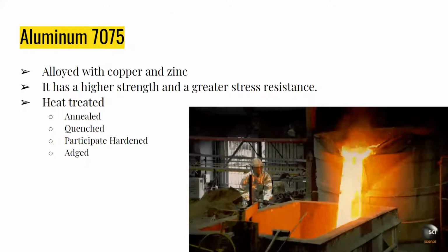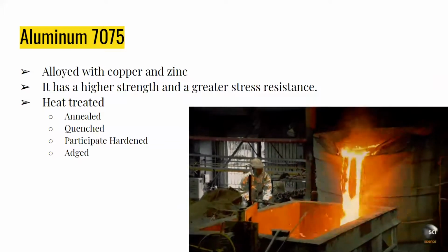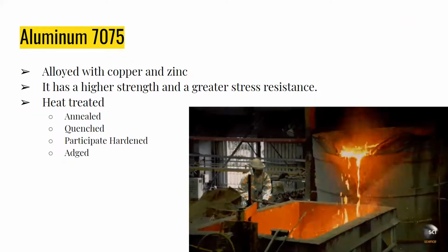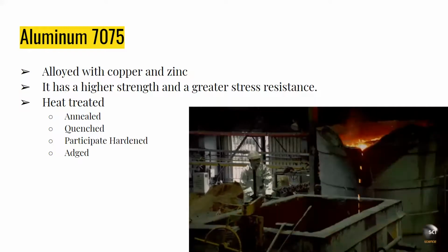Another widely used material is 7075 aluminum. This material is alloyed with copper and zinc for maximum tensile strength after heat treating. It is used for areas that experience a lot of stress because it is one of the strongest alloys available. The alloy has a great strength-to-weight ratio and keeps its properties at low temperatures. That is important because airplanes can experience drastic weather changes at high altitudes where temperatures can plummet.